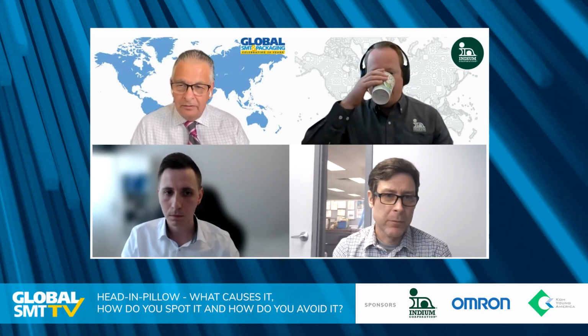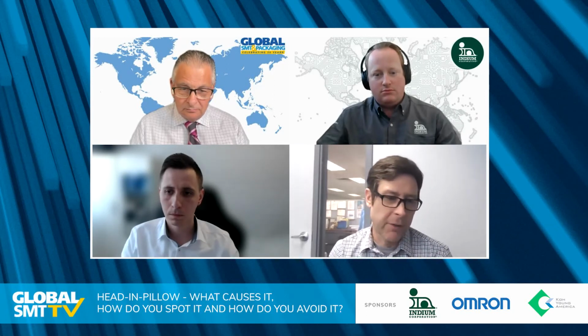Okay, so Kevin, we'll give the last word to you on this topic of the mismatch or potential mismatch between using SAC 305 and different alloys. Do you have a view on it? Yeah, actually, there are some cases where you can have mixed alloys and even end up with very, very good performing results. And what you have is a heterogeneous solder joint, basically. And we've seen very good results from that, actually, in how the stress is applied to the package. So there can be actually benefits in that case.